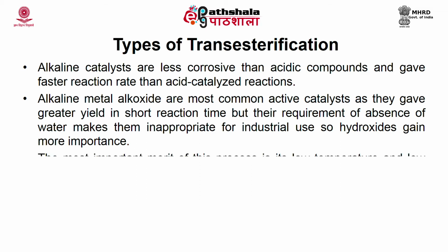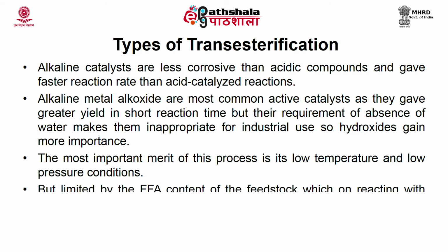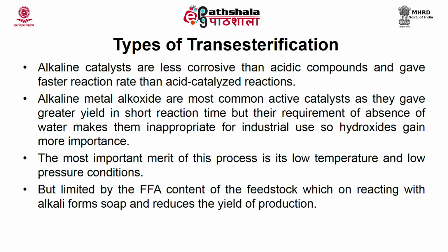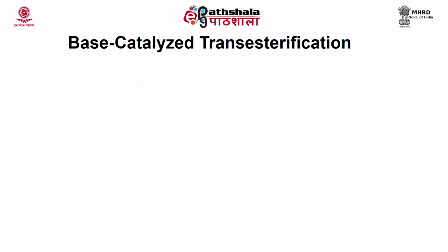The most important advantage of this process is its low temperature and low pressure conditions. So, it can be conducted at normal room temperature, but it is limited by the free fatty acid content of the feedstock, which on reacting with alkali forms soap and reduces the yield of production. Normally, the preferred FFA content for this process is in the range of 0.5 to 2%. This is the mechanism involved in this base-catalyzed transesterification. It involves 4 steps: reaction of base with alcohol to form alkoxide with protonated catalyst.